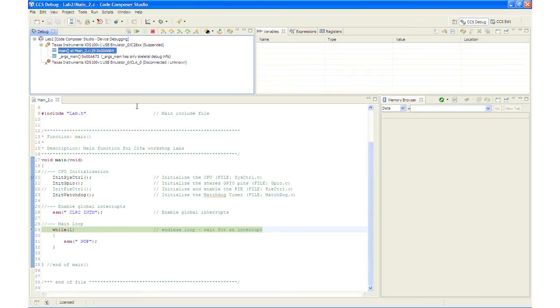The watchdog at this point has been disabled, and so we don't expect anything to happen. The breakpoint is being set on the top here to prove that the watchdog is disabled. If the watchdog caused a reset, code execution would have stopped at that point there. So as you can see, we are still sitting down in that main loop in the bottom.